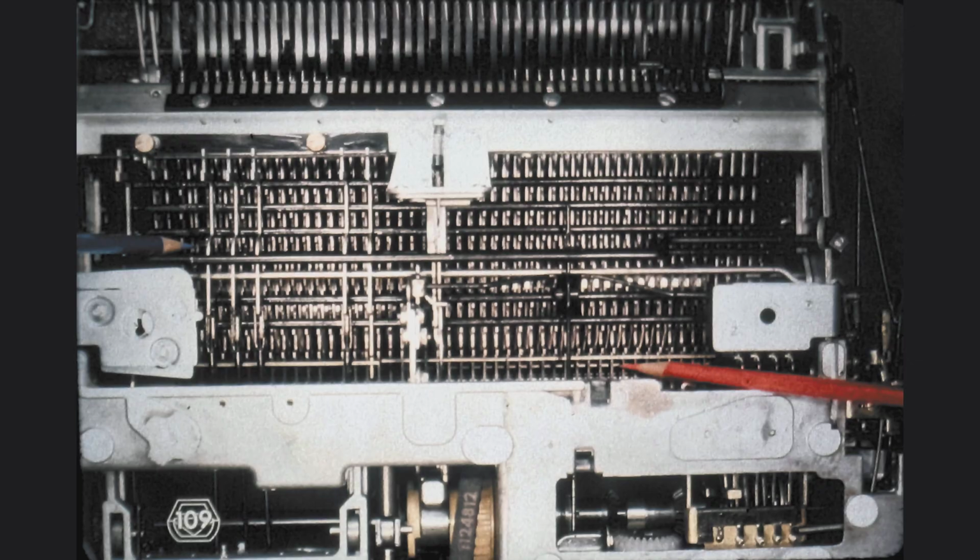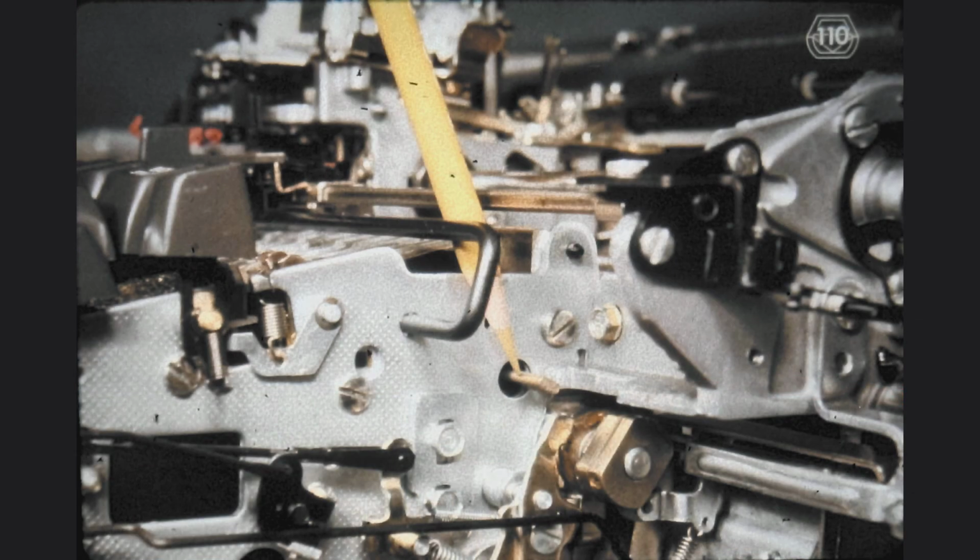A closer examination of the lockout bail shows that it also blocks the depression of the character interposer by placing the keyboard lock lever, at the blue pencil, into the compensator tube, at the red pencil. The end result is that all of the character interposers become blocked for as long as the on-off switch is in the off position. This, of course, works only if the amount of play between the steel balls and the compensator tube has also been adjusted.